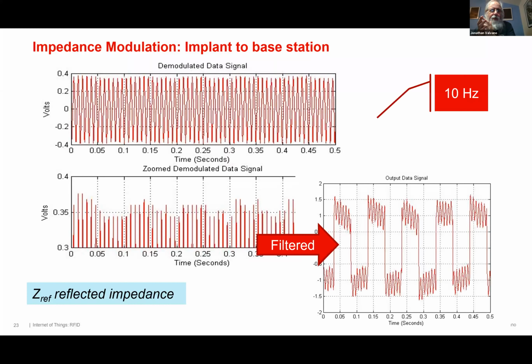All right. Here's some of our signal. So we were all excited. We got two very exciting moments. One, when we could power the device and we saw the LED flash on the device. And then this one, in the lower right, is the filtered, demodulated output, because you remember the GPIO pin on the embedded device was oscillating at 10 hertz. And this is the filtered, scaled signal on the base station, which showed that same 10 hertz.